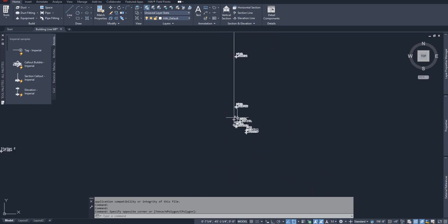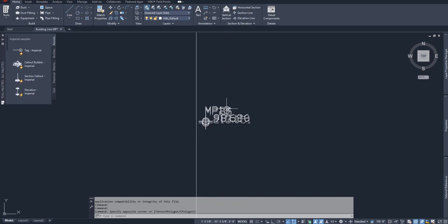And when you export them, you can export them as a CSV file, so they come up in Excel with their coordinates. But another way you can export them is as a drawing format, so you can simply upload them into AutoCAD very quickly and then align them to whatever drawing you have available to you. I want to review how to make sure that these points look clean before you do any sort of alignment. This video is going to be very simple.